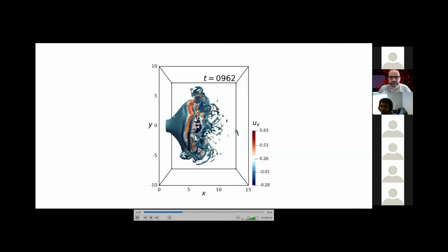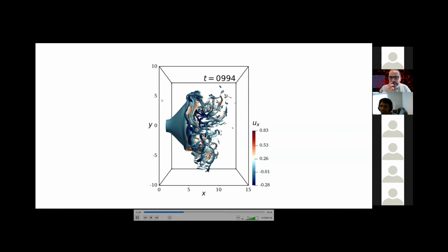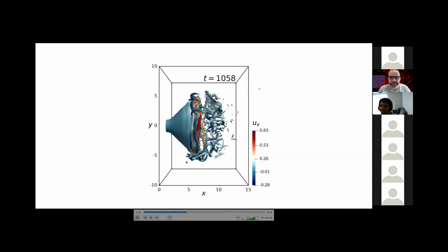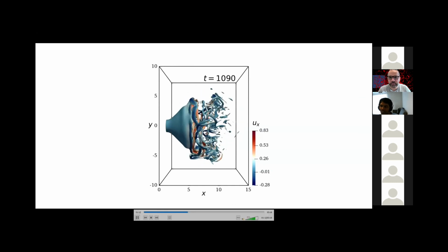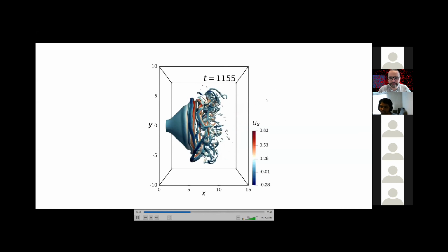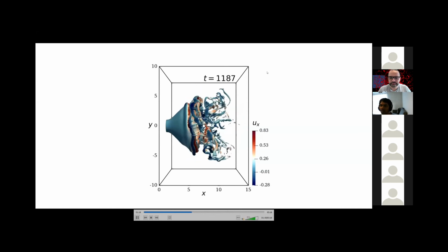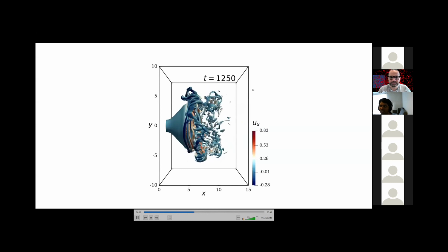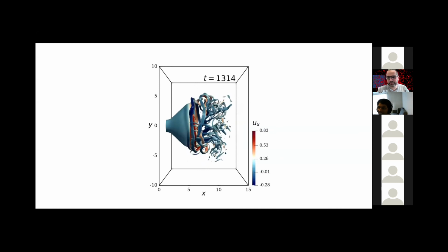I'm assuming that you would be including a co-flow in your jet simulations. That would reduce the amount of recirculation that you get. I also have a 1% co-flow. In addition to that, by including the buffer zone at the outflow, I was able to suppress huge problems at the outflow conditions. Very good. Same conclusion as us.